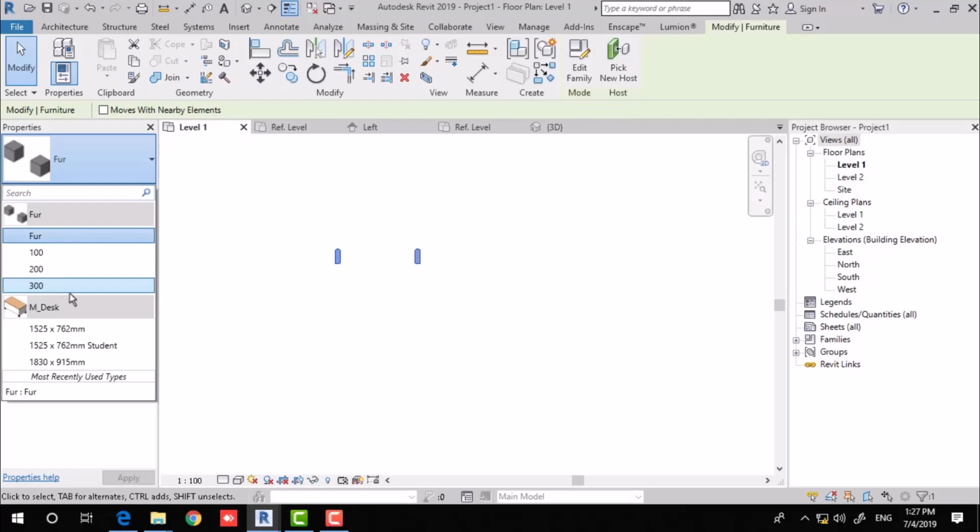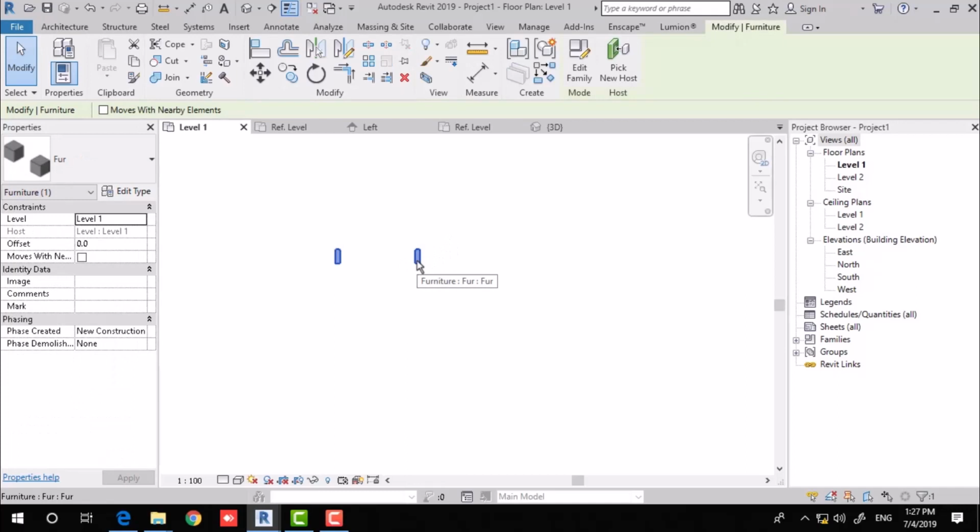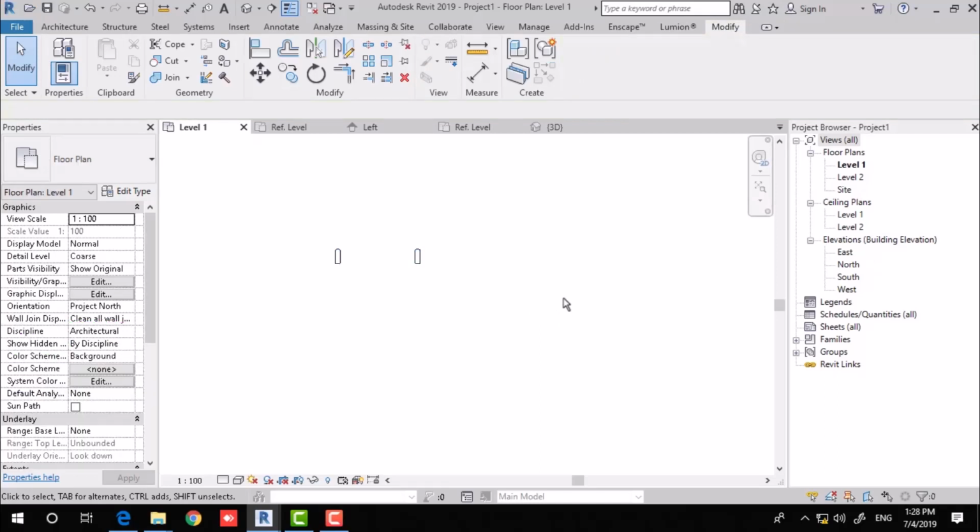And as you know, sometimes we load a specific object or a family, a door, a window, or what else, which has different types in different dimensions, which means that the type has been duplicated but the dimensions are modified. But in later sessions, I'm going to teach you another thing related to this issue, which is associating a catalog to the specific object. In the window of the catalog, you can specify the desired type that you want in the project. So in the future sessions, I will teach you how to create catalogs, which has some simple code scripting that I will tell you later. So the second topic was how to create different types of a specific family.